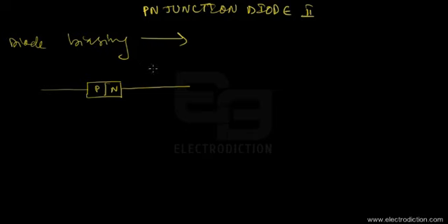It's basically because we know that in order to cause current flow through a P-N junction, when the barrier field opposes the motion of the majority carriers through the junction, we need to impart an energy of E, which is the barrier energy, to our majority carriers so that they could cross over the junction and flow.